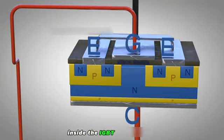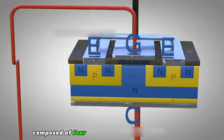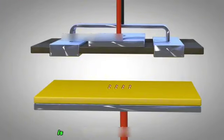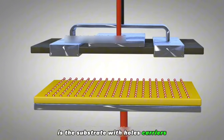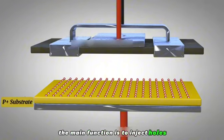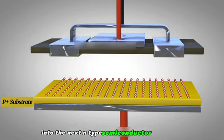Inside the IGBT is a collector composed of 4 layers of semiconductor material. The first layer on the collector is the P+ substrate with hole carriers. It's also called the injection layer. Its main function is to inject holes into the next layer, the N-type semiconductor drift layer.